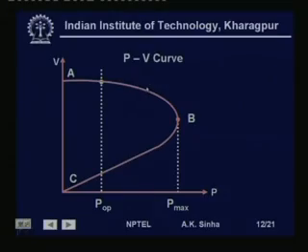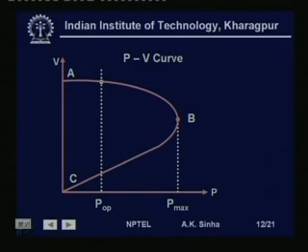will keep on dropping, and this process will be accelerated as we come closer to the maximum load that is possible. We call this point, or this voltage, the critical voltage, that is, voltage below this cannot be sustained by the load. After this voltage, if any drop takes place, then it is a runaway situation and the load is completely lost.